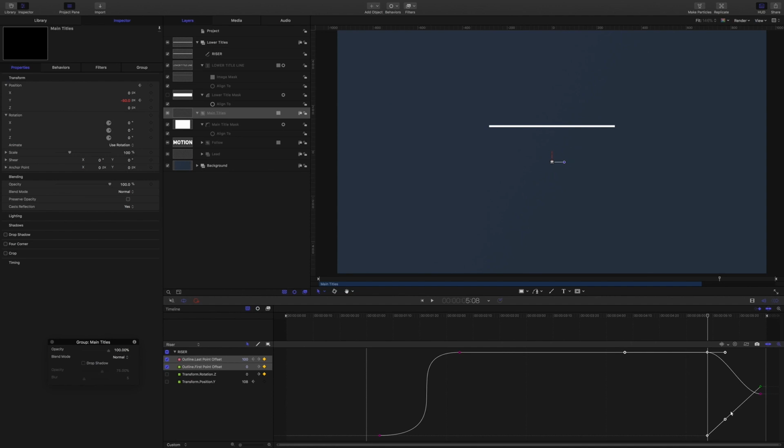So I'm going to group select these curves here. I'm going to hold the shift key on my keyboard and drag to select them. It should straighten them all out. I'm going to pull them forward. I'll bring that playhead to that 5 second and 15 frame mark, so we've got a good reference point here. I'll grab these handles and drag them out. So we want to have that steep part of the curve sitting around where our playhead is meeting. That's a bit too far forward. How about bring them forward this way? Alright, so if I turn the Z rotation on, okay, let's see how that looks.